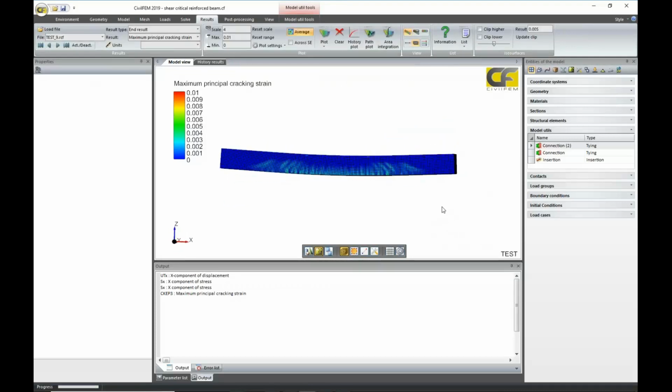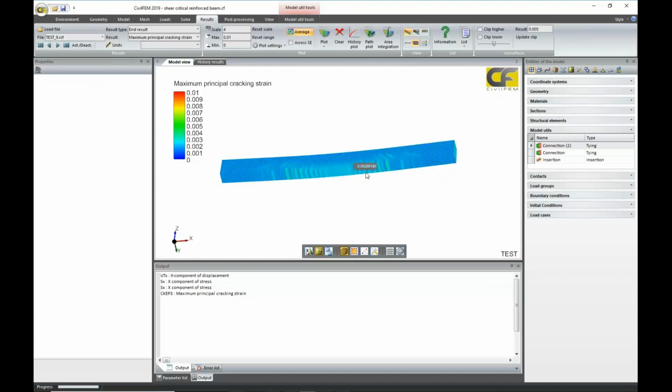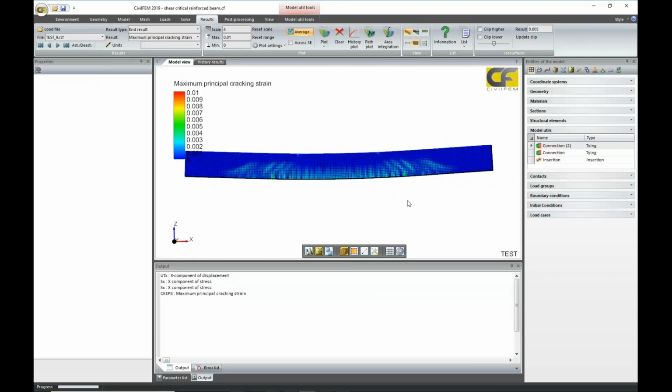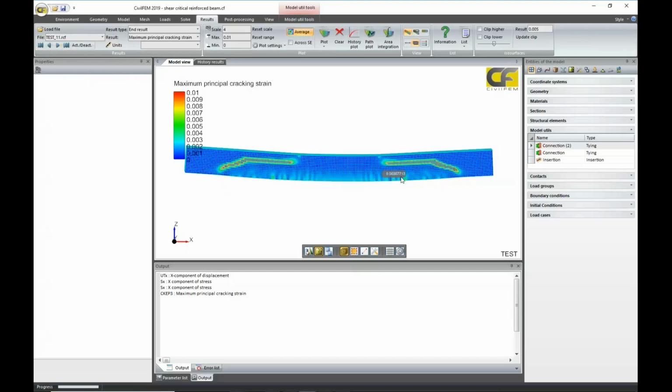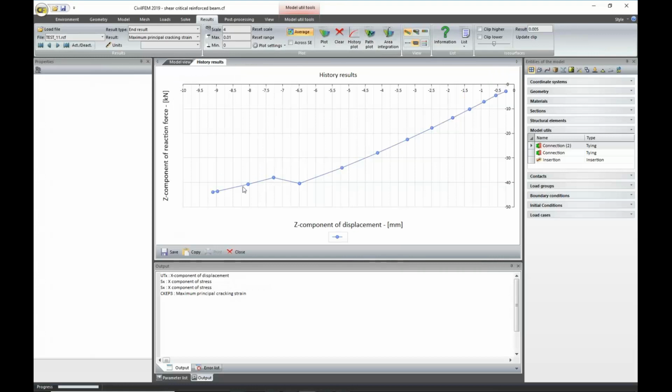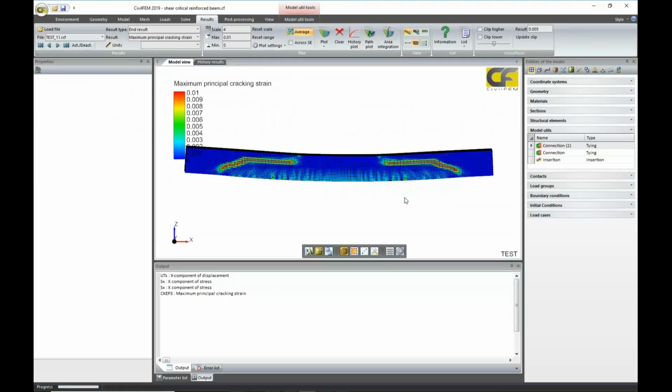So well, I have at this point some cracks, but not very wide. Mainly here I can see some shear cracks are higher than the bending ones, on both sides, but still not too high. So I increase the load, advance to next step. Next step. You can see shear cracks are developed following 45 degrees from supports. Suddenly a huge crack is developed, so it means collapse at this point, which is this point here. And then we have some other steps that were solved, but you can see this is just complete collapse.